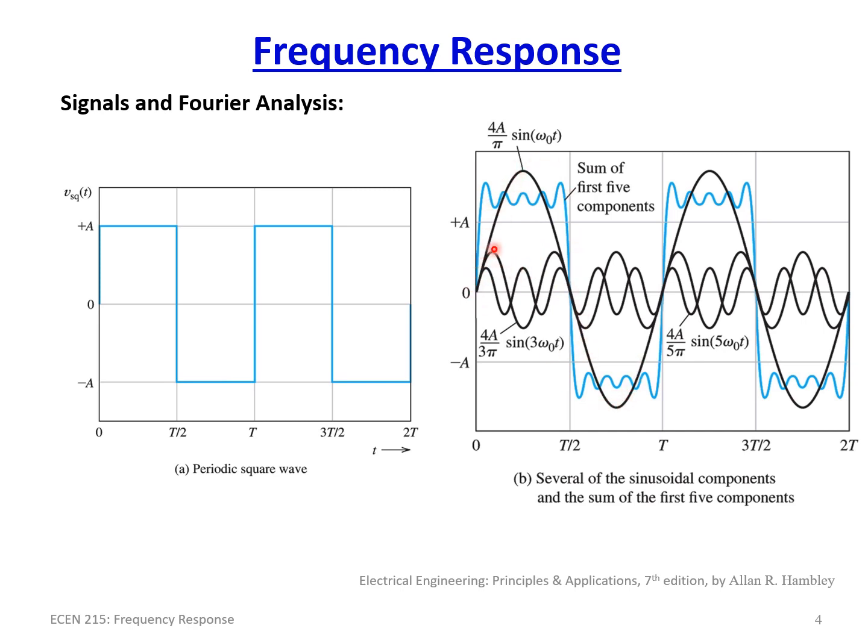And then you have another one that's, again, double the frequency and quadruple the frequency, so on and so forth. Again, it takes a lot of frequencies of sinusoids to end up creating the actual square wave. But mathematically, it can be done, and in principle, that's what we actually see on the oscilloscope.